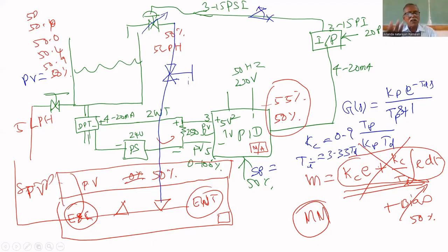Now we have to transfer from manual mode to auto mode. For that, 3 things you have to note down. Whether the process is at steady state. By this time it will be at steady state because you took 20 minutes to calculate. That's why the process is at steady state. Now make set point equal to PV. Whatever the PV, you make that the set point. Now the tuning parameters are entered. How to enter tuning parameters? When the display is SP, set point, at that time if you press escape, it will ask for Kc and Ti. You can enter those values.